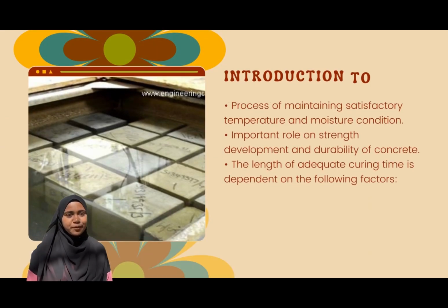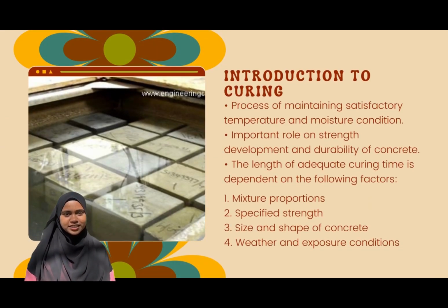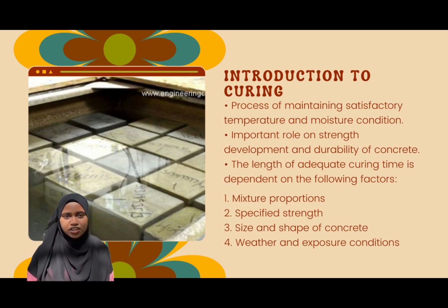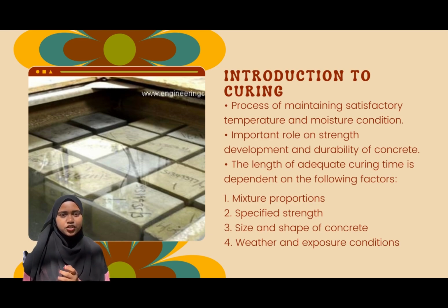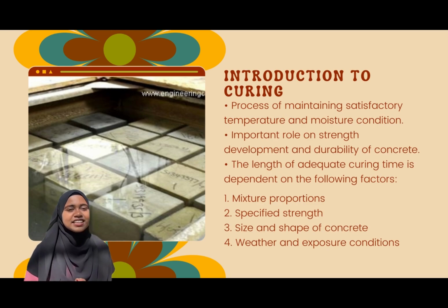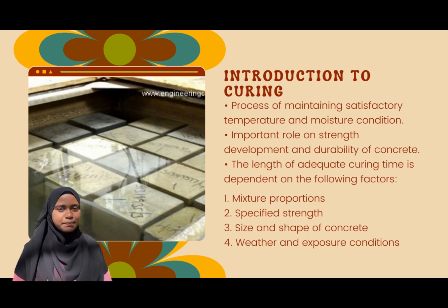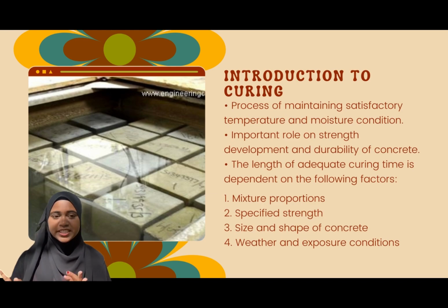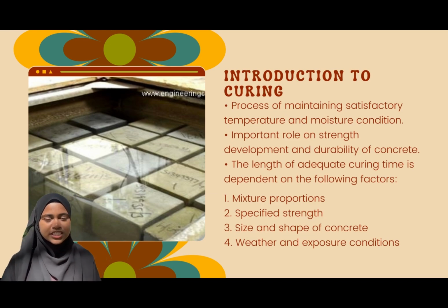Curing process. Curing is the process of maintaining satisfactory temperature and moisture conditions. It plays an important role in strength development and durability of concrete. The length of adequate curing time depends on the following factors: mixture proportion, specified strength, size and shape of concrete, and weather and exposure conditions.